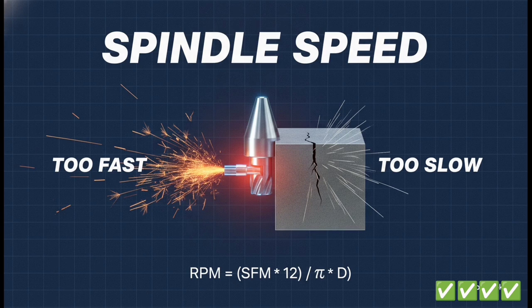Driving all of that mechanical motion is a very strict set of mathematics. The spindle speed equation, denoted as N, is essentially the mathematical heartbeat of the machine. You see, engineers don't just guess how fast the spindle should spin. No way. They calculate it precisely based on the desired cutting velocity for the specific material being machined, plus the diameter of the cutter. Getting this equation right is absolutely crucial. Run it too fast and you're going to burn out the tool instantly. Run it too slow, and you risk tearing the machine apart through excessive friction.